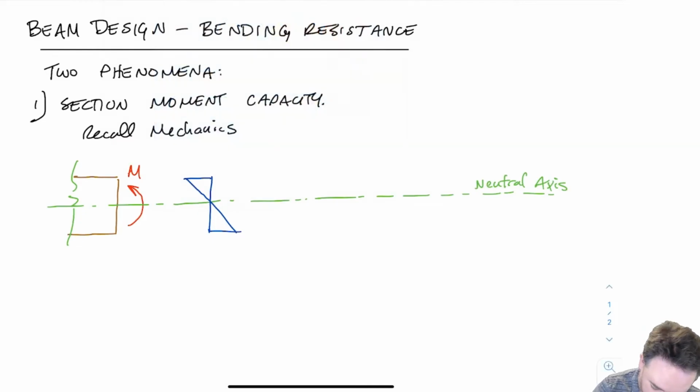So here I have the strain, and our strain profile is linear. And remember, typically for typical members in construction, we are assuming that these members are Euler-Bernoulli beams, so that plane sections remain plane, and our strain profile throughout the depth is totally linear. We have compression on the top in this case and tension in the bottom, and in between our strain has a linear profile, and at the center where we have the neutral axis we have zero strain.